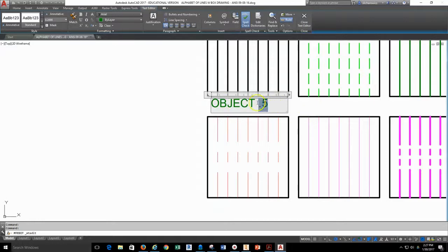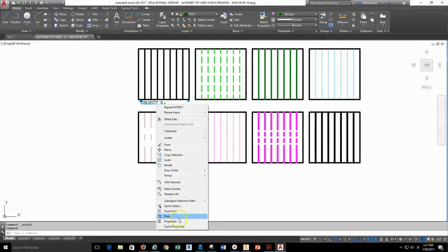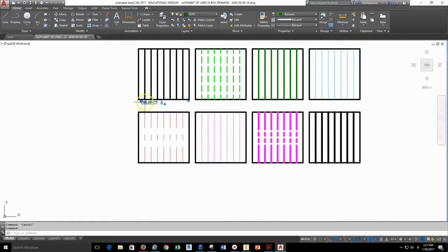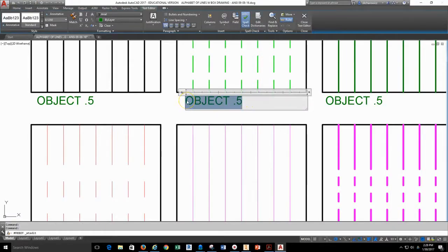To change the size, text can be highlighted, and then text can be changed in the text size dialog box at the top of the screen. Text size can also be changed by selecting the text, right-clicking, and going to the properties of the text. Text size is available on the properties. This particular text can then be copied, and by moving across horizontally, it keeps all text aligned. Then text can be selected by panning window and then copied as a unit all 4 down to the proper position. You can then double click on the text to then go in and alter the actual text.